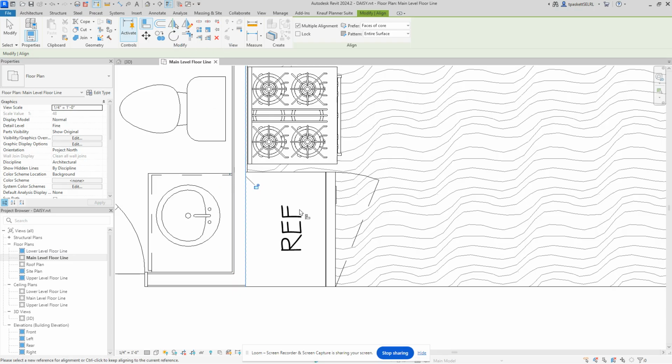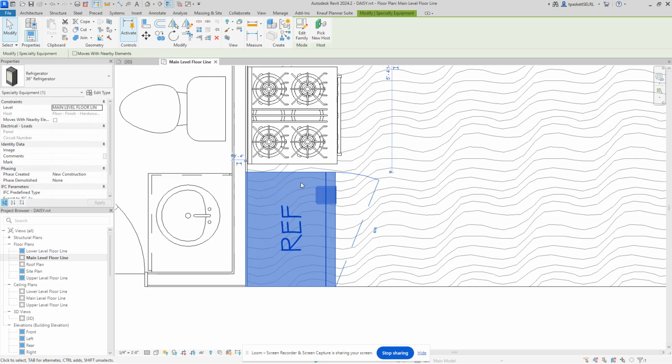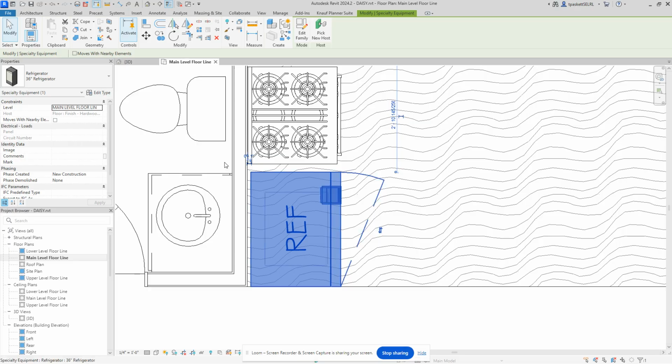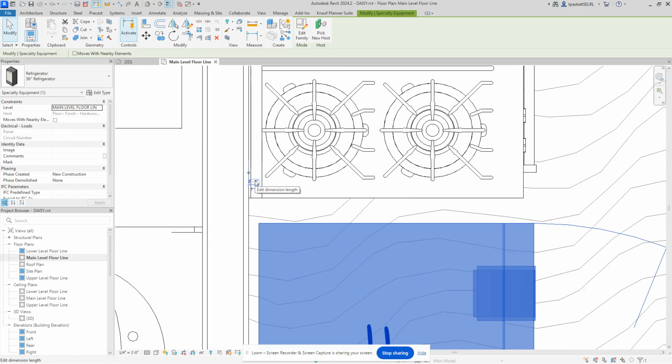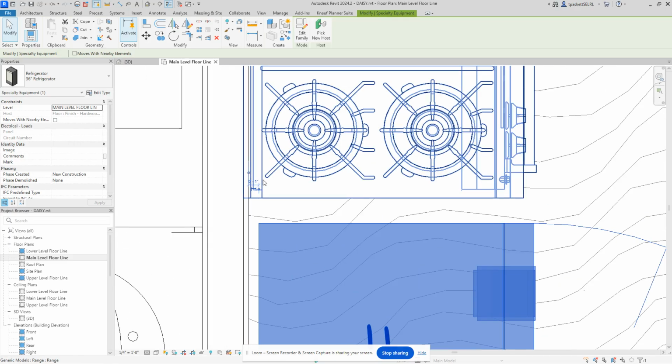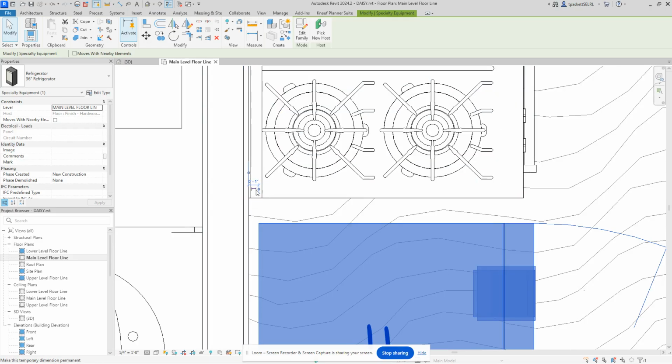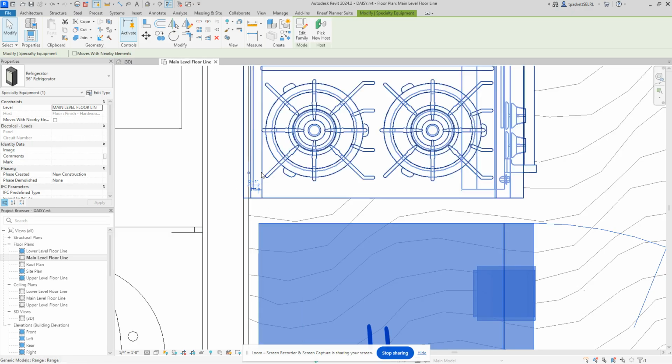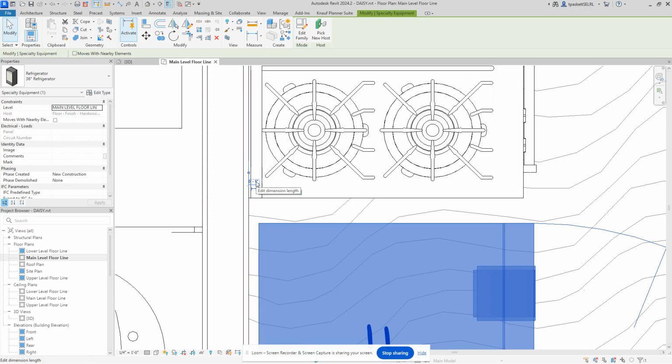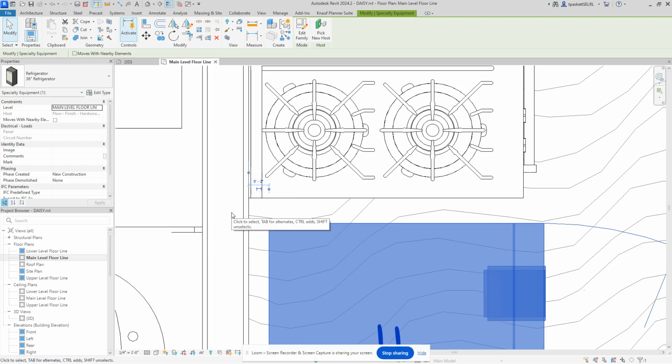So if you move that, you can select it with the modify. You can use your arrow keys and just space it over. And then there's this little temporary dimension. Now these get you precise. And I know it's a lot to throw at you. Once you get these little temporary dimensions, you can click on the number and tell it exactly how far to go. And that is your parametric dimensions. So you'll control exactly where you place things.